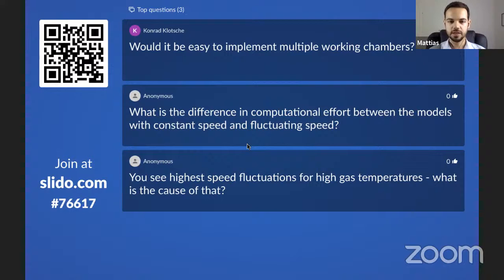And regarding the evaporating temperature, there is a mixture. It's maybe not so relevant regarding the loads, but it also influences the mass flow and so on. So you really need to make this map. It's not so linear, let's say, on both sides, on evaporating and condensing temperature, but we have the tools to do that, and that could also be done experimentally. So from there, we only took the information of which conditions we wanted to focus on in the study here.